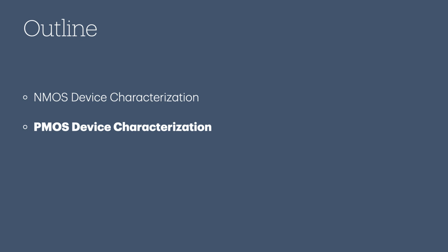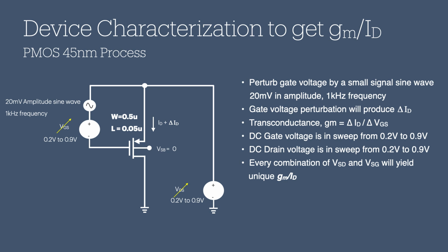PMOS device characterization. Characterization of PMOS is the same as NMOS, except the connections are inverted, as shown. The same concept is applied. This is the GM over ID setup. The student is encouraged to study them on their own.